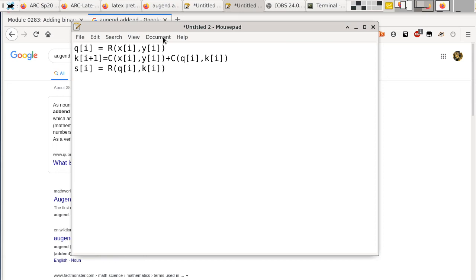All right? And then we also look into the truth tables, and we find out that R is just exclusive OR. Because when you work with binary numbers, xi is only a 0 or 1, yi is also just a 0 or 1. So the function that we need to do to figure out the partial sum can be implemented using logic gates or Boolean operations. Okay, so R of, I'm going to use another set of symbols here.